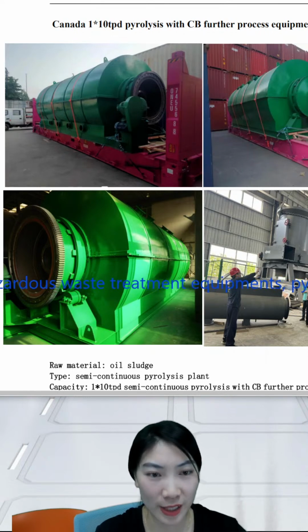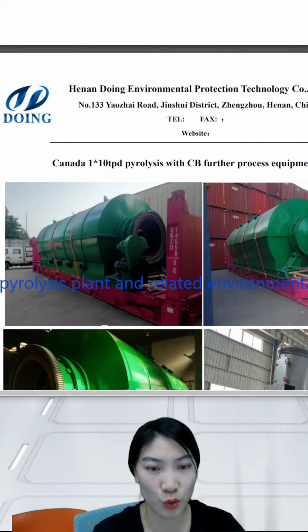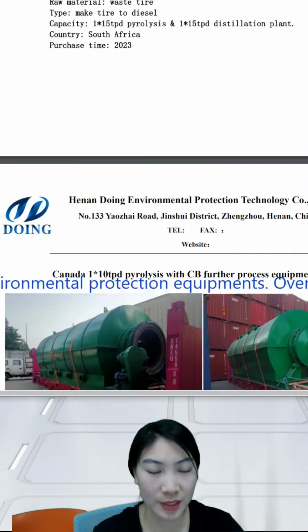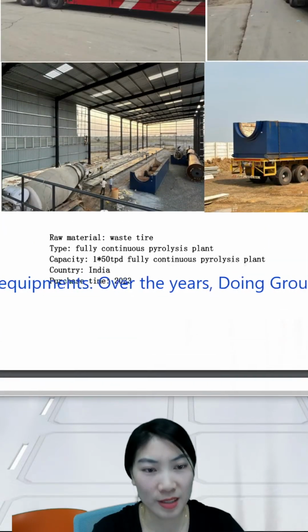The oil yield is very good. Normally, if your raw material is oil sludge, we suggest you use a stainless steel reactor plate because it's more anti-corrosion. But for used tires or plastic, normal carbon steel is enough.